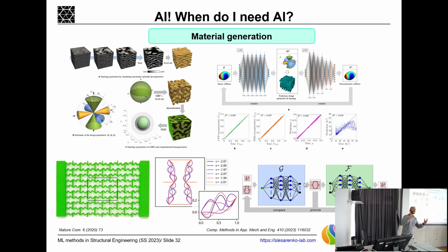So it's not like you're looking at a material and saying, okay, this is a property that this material has. Now I'm asking: I would like these particular properties. For instance, for a bone implant, if I have a broken bone, I would like to put something inside, but I don't want it to be steel, because in this case you will have an enormous mismatch between the stresses, because steel and bone have very different Young's modulus and other mechanical parameters.